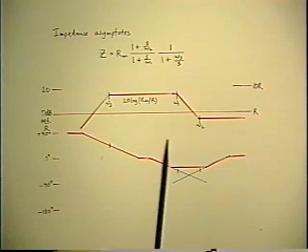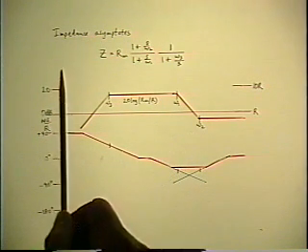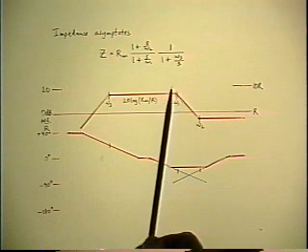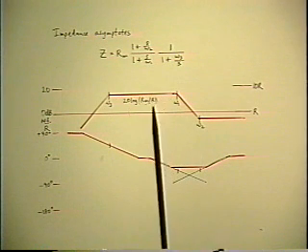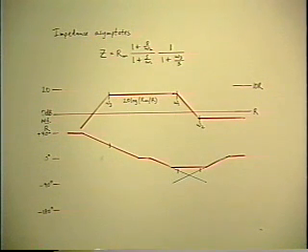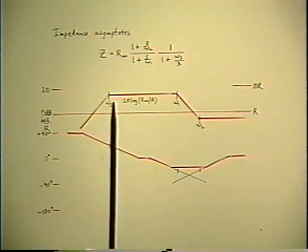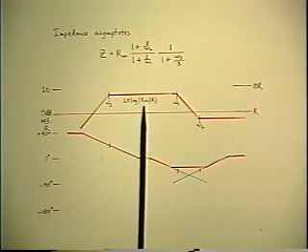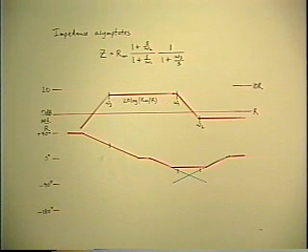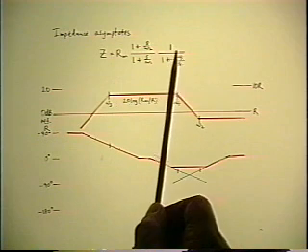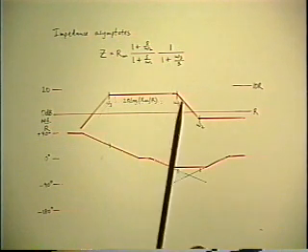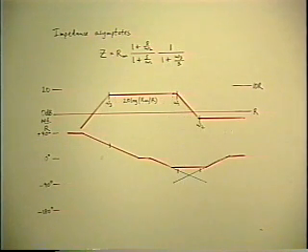Now, what sort of scale should we choose for this? Remembering that this is a logarithmic scale, or at least we'd like to keep it logarithmic. There's no point in changing the structure of the diagram just because we're talking about an impedance instead of a voltage gain. And we can still use exactly the same asymptote structure, remembering also that the smooth corners go along with it as well. The actual curve for the magnitude of the impedance versus frequency, of course, has smooth corners just as the voltage gain did: 3 dB down points and 1 dB points and so on.